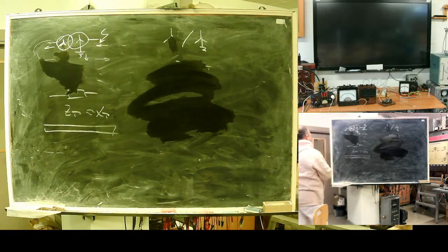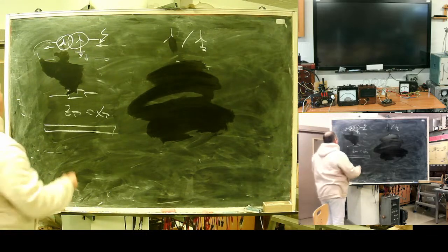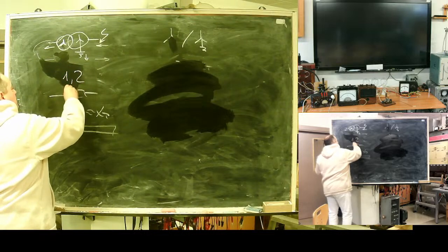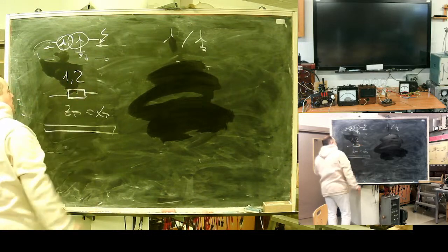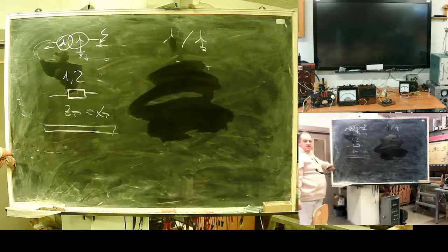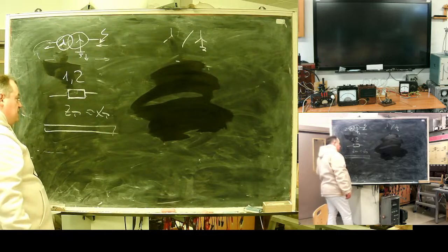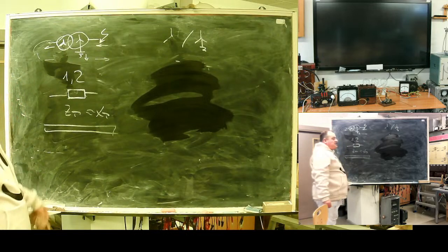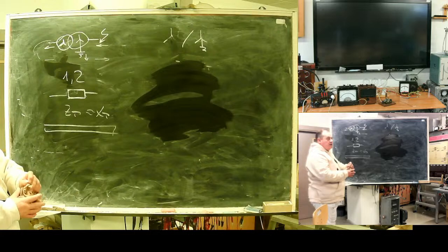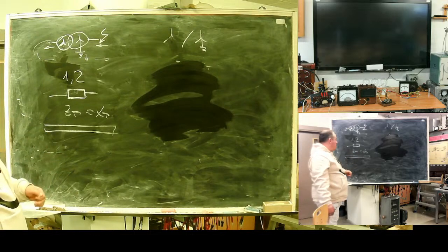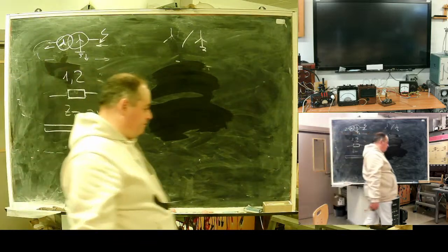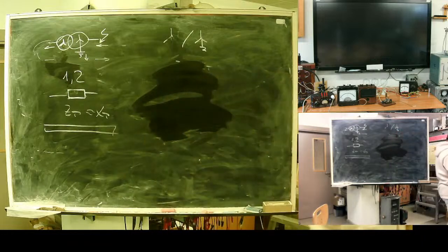Here, you should be careful. For direct and negative sequence, everything remains the same. Transformer resistance found from the short circuit test. For zero sequence, here you should be aware.